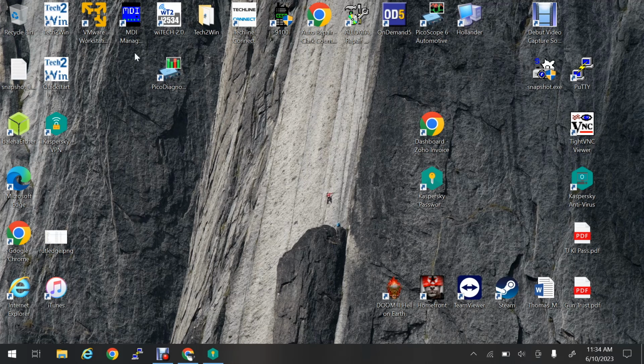And so next time I think I'll go into Ford and how I work with those. It's kind of the opposite. I program Fords with a VX Diag and I use the Ford IDS software with the VCM2, because the new JRS or whatever that you program with doesn't recognize the VCM2. So it's kind of that way when you're working with Chinese scan tools.